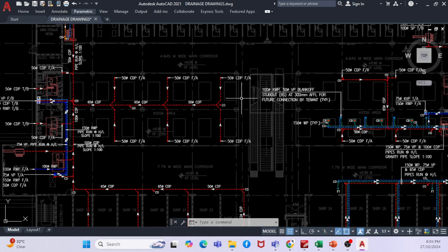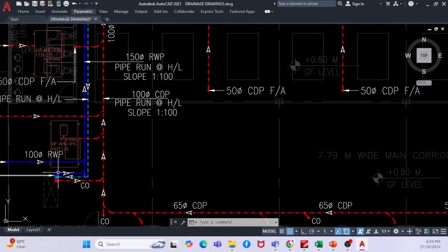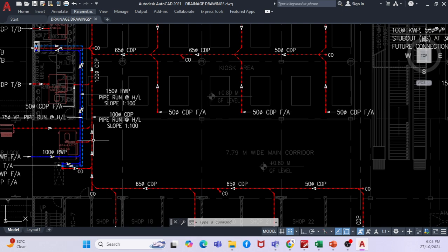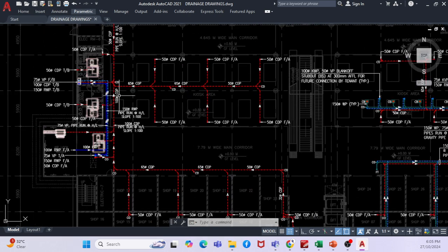What is the condensate drain flow? So based on the condensate drain flow, you can calculate the pipe size based on the standard, right? So this is all waste from the condensate from the HVAC equipments. Condensate drain from HVAC equipments. Basically, you can see this is AHU and you have a condensate drain. This is the FCU. You have a condensate drain, right? Okay, so this is one of the waste pipes, the condensate drain pipe.